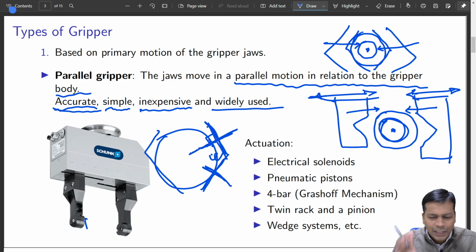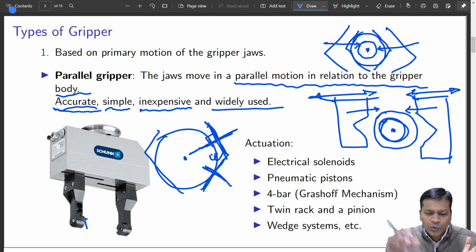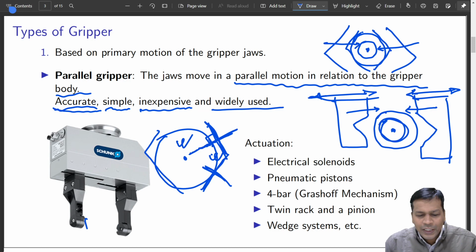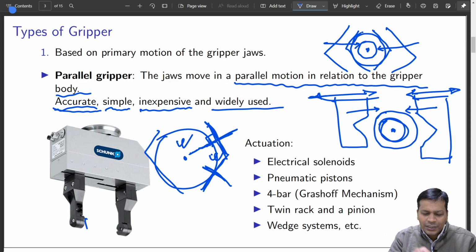That means a calibrated position. Once it is held, you know where the axis of that cylinder is. So the axis of the cylinder is not going to change. That means you can do a planned movement of this particular cylinder which it holds. It won't just hold it, you can precisely manipulate it. If you want this cylinder to be inserted into a hole, you can easily do it. If you know the hole location precisely, you can just align your robot axis and insert it.